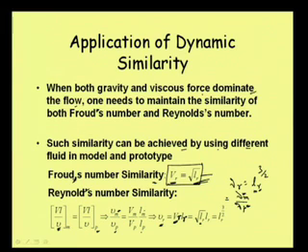So, sometimes we can take two fluids that we decide we will be using in the model and the prototype. So, we can find out what will be the ratio of the kinematic viscosity. Once we get this ratio, then we can size our model, we can know what our length ratio is. Because if this ratio is fixed for two given different fluids, we know this ratio, and from that we can find out what our length ratio in the model and prototype should be.